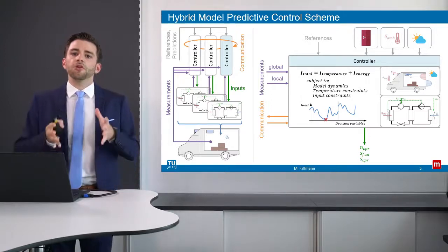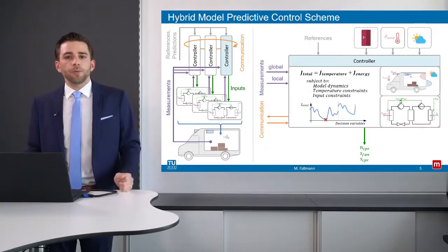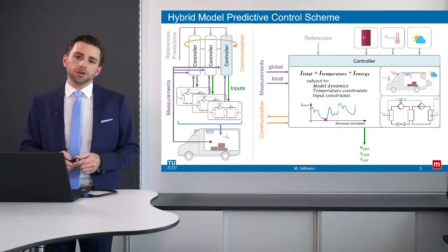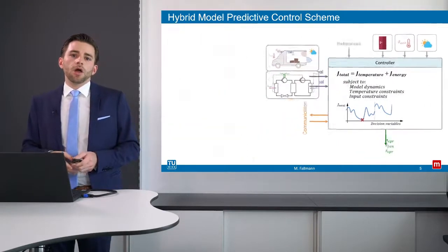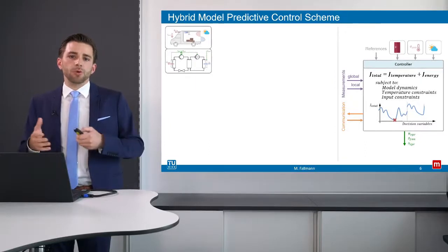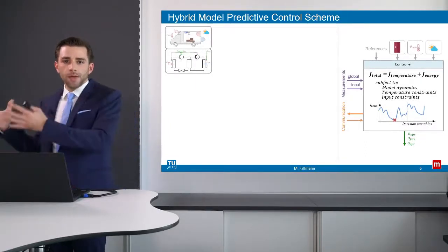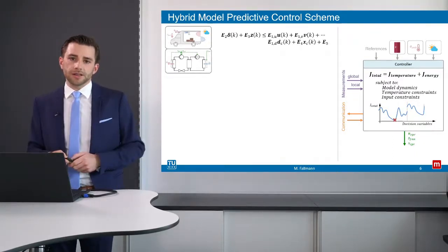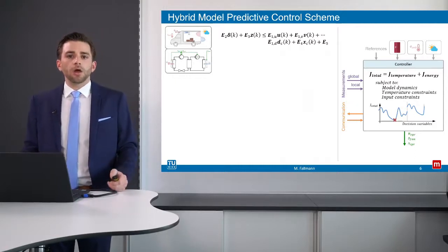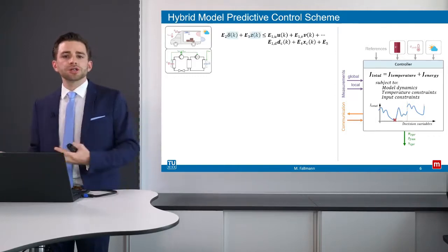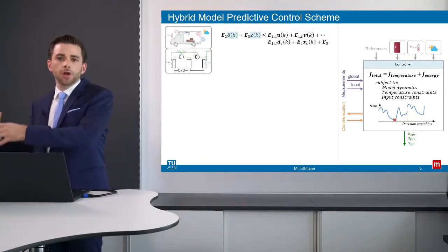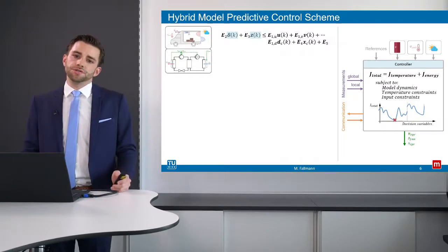By now, we have drawn a very shallow picture of what hybrid model predictive control actually is. So let's dig a bit more into the equations underneath. Under some mild conditions, it is possible to transform a hybrid model description into a series of inequalities, and these inequalities may look like this in a very general form. E are constant matrices, delta and C are binary and continuous auxiliary variables that are necessary to allow the transformation from the hybrid system description into a series of inequalities.